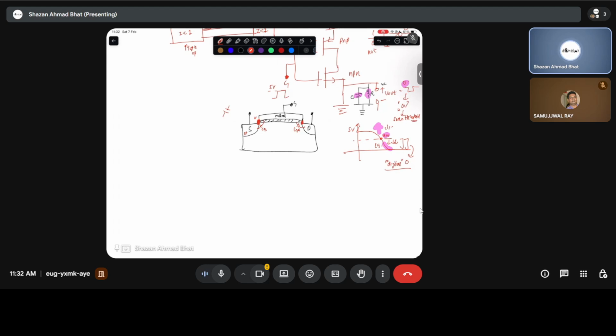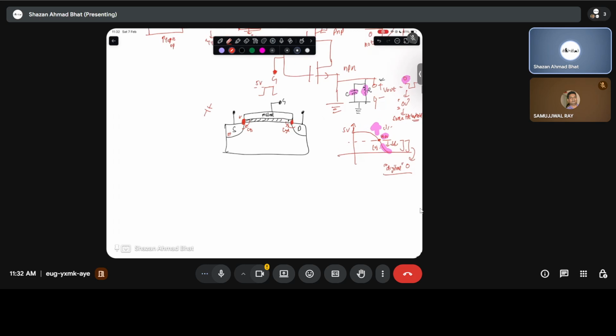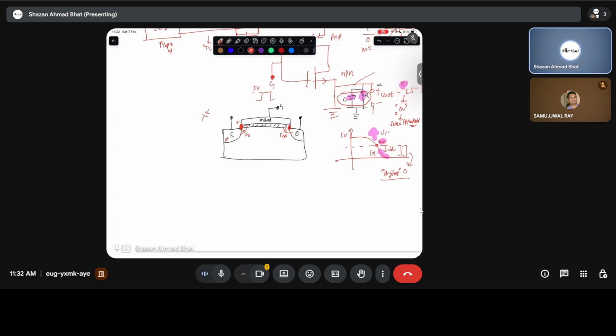And they also have resistance, because resistance is intrinsic whenever electrons flow inside a certain system. This gives rise to a particular RC network at the output end. And once this RC network is there, it gives rise to a time constant, which is R times C. This time constant is another delay time, which is seen at the output.